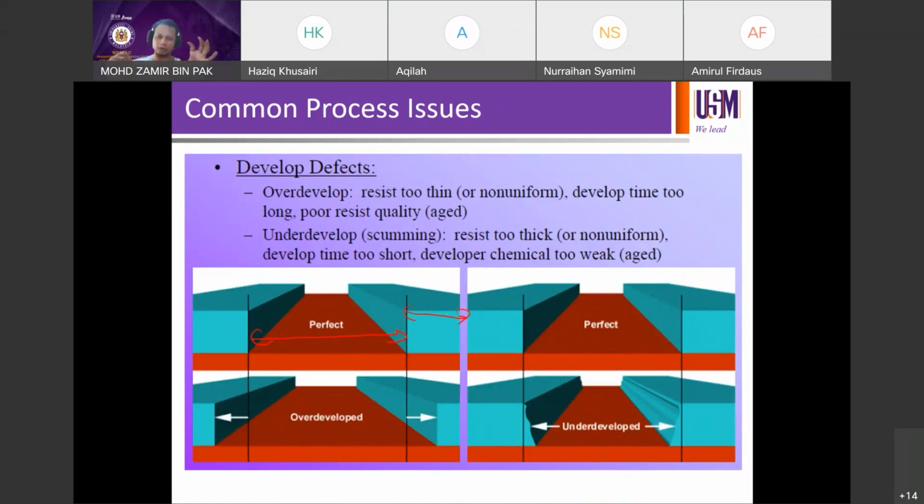It depends on the algorithm defined on the SEM. If you define it to measure the space, it will always find the space between features. If your algorithm is defined to measure lines, then the SEM will always find the lines to measure. Whatever is measured is reported on the SPC chart as drifting on the high side or drifting on the low side. So that will go back to the algorithm.